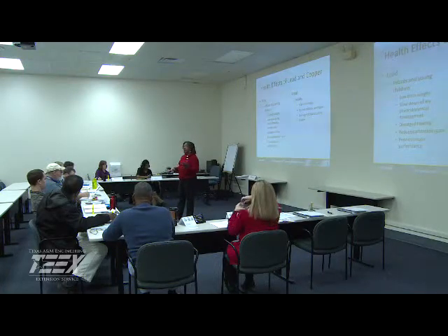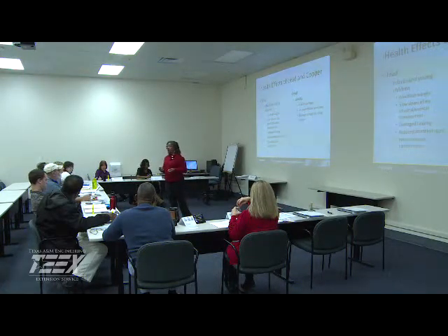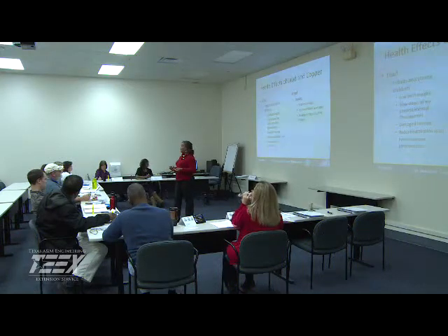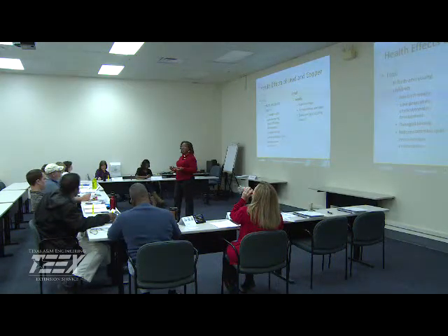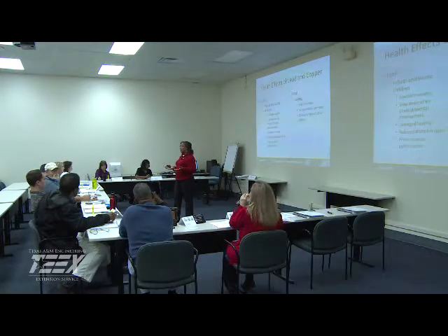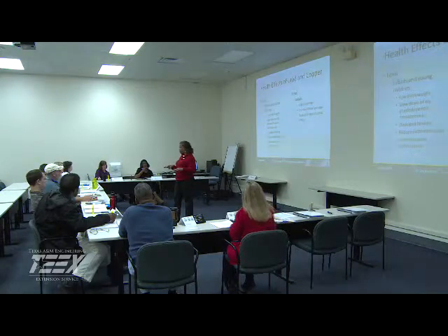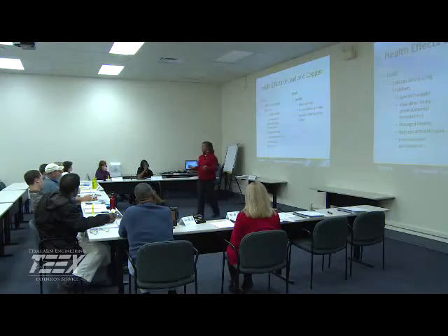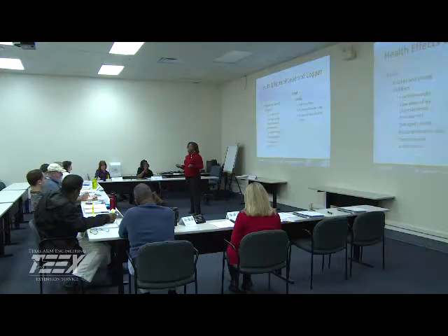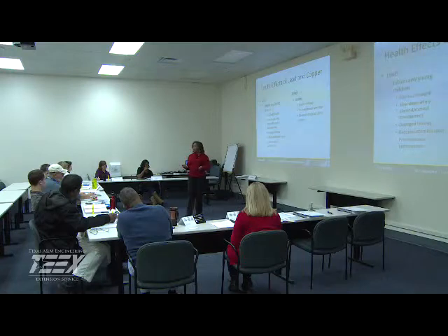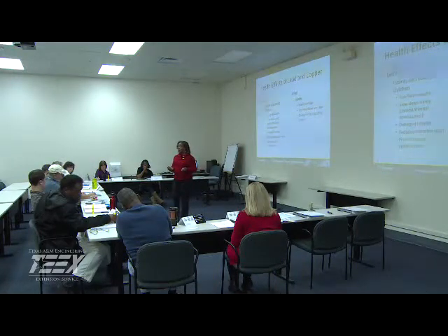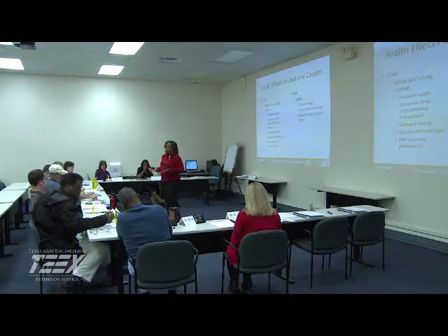Because the state keeps saying we don't have one, we have an action number. And the state maybe doesn't have an MCL on the test either, and I'll have to defer back to the state agency. Maybe they're using action level and MCL interchangeably. I'm not sure if that's what's happening. But when you look at the EPA rates, 1.3 parts per million is the MCL. It's on your primary drinking water standard. 1.3 what? 1.3 milligrams per liter, parts per million.